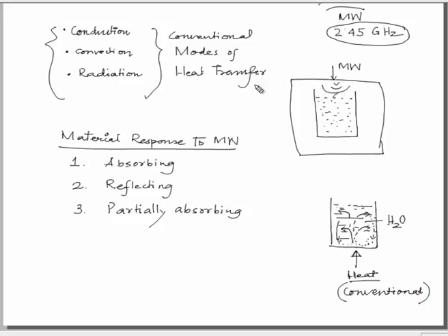However, in case of microwave heating, this is same water, we can expect similar temperature at the same time as in this layer as that of in this layer, unlike here. That is why in conventional heating process, although the temperature at the bottom of this pot or the cup is high, this layer temperature will be much less initially. Say this is T2 will be less than that of T1 initially.